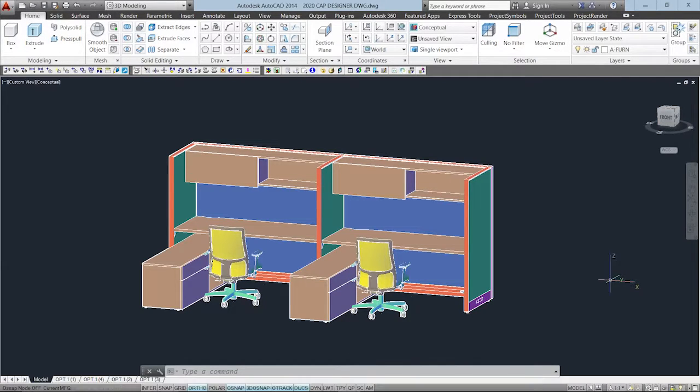Okay? So all right, let's begin with our CAP design author DWG files. So what you basically see here is the author DWG that was created by, let's say, myself or a design team. The one thing that you should really understand about a CAP design or a CAP authored or one of these authored spec tool files is that they carry what we call attributable information. This information is carried forward with the actual model or specific item that we're looking at, that actually tells KITS which manufacturer it is, what catalog it's from, what it is,